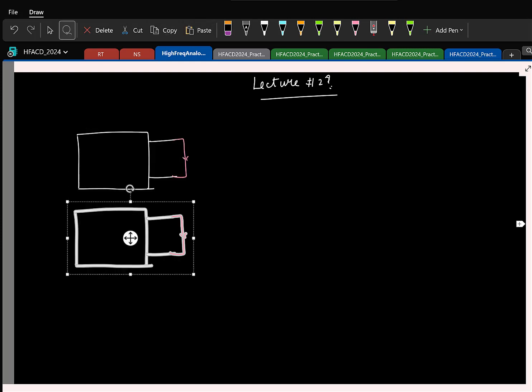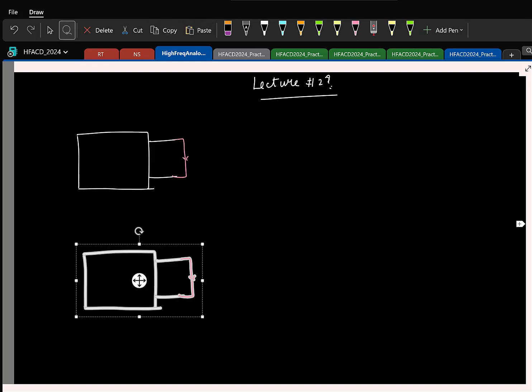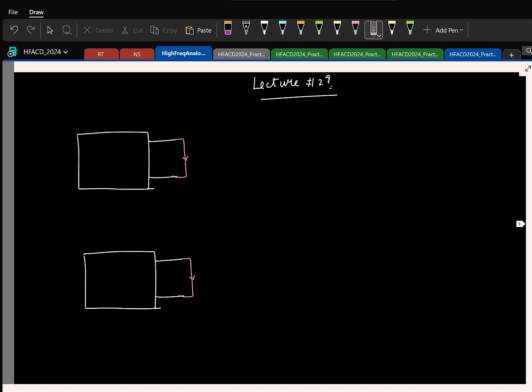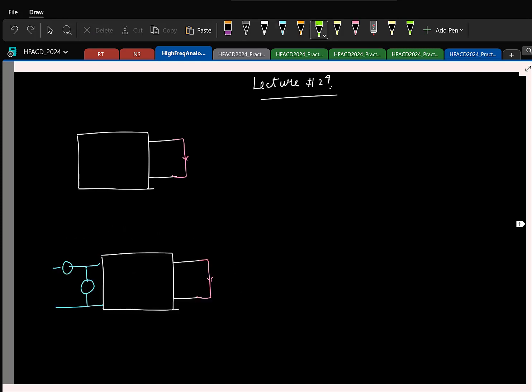We say the network is noiseless and model the noise using something at the input. We need both a voltage and a current source to properly model the noise for any value of the source resistance Rs.